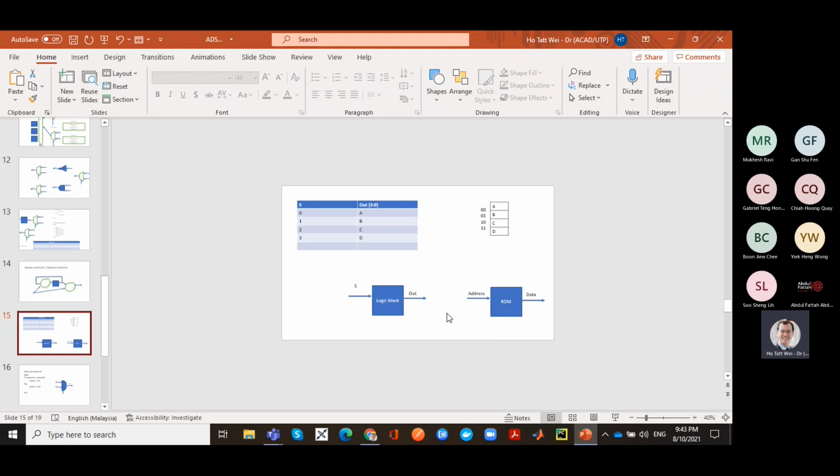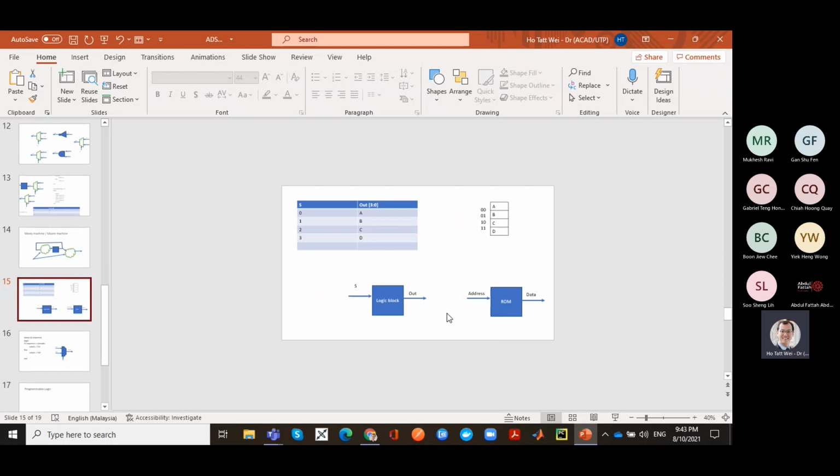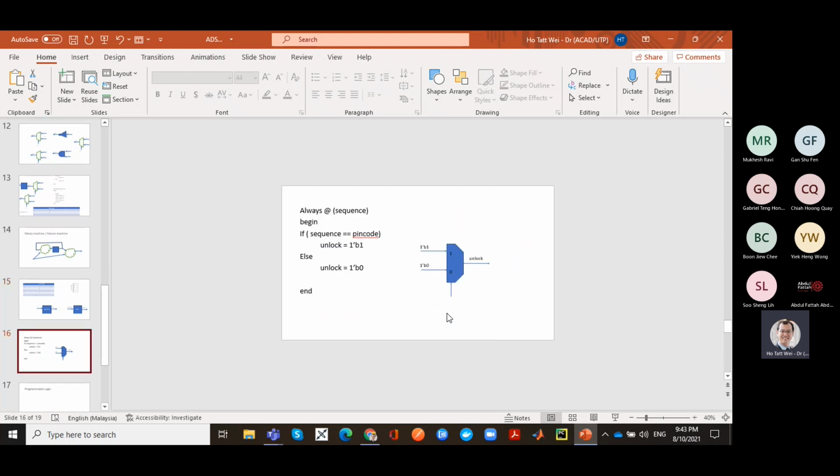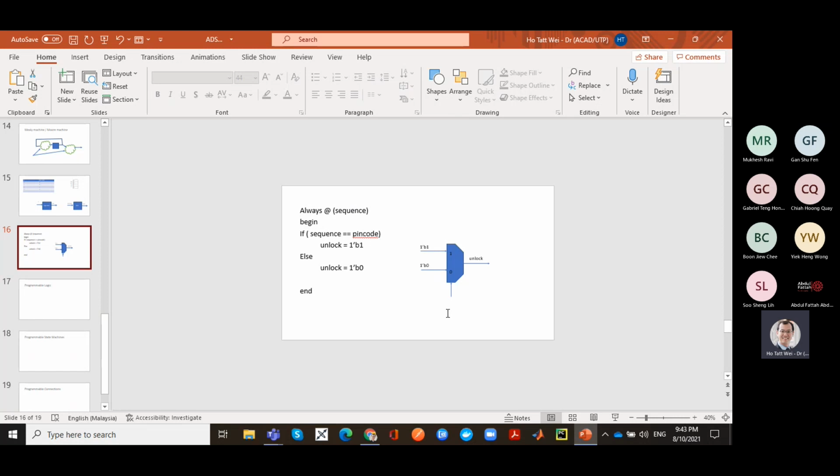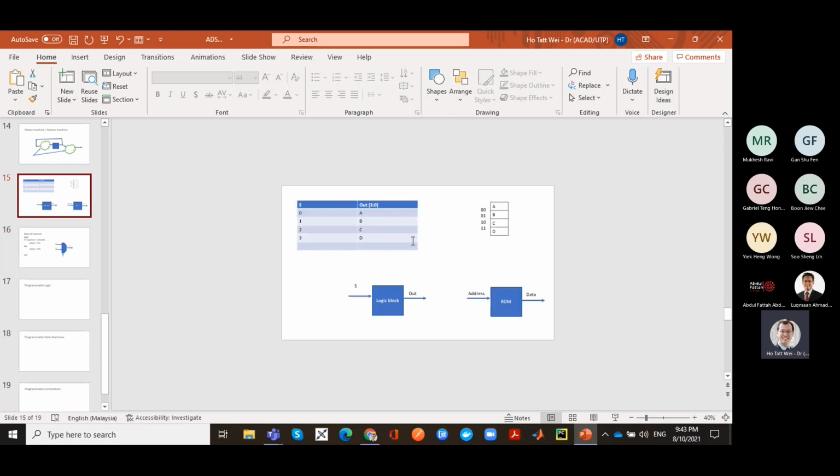The other concept that we briefly talked about is that beyond a multiplexer, I can also implement any combinational logic using a memory element. A combinational logic is nothing else but a bunch of input signals, where for every possible combination of bits in the input signal there is a described output signal.